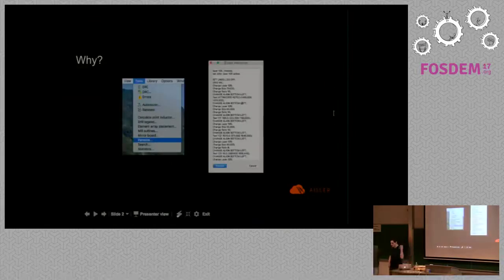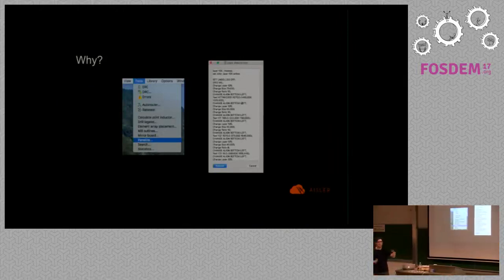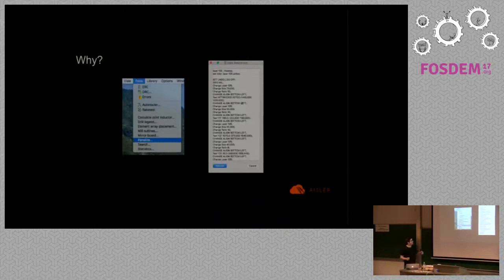So has anyone of you seen these windows here? They are out of Eagle, CadSoft Eagle, Autodesk Eagle, whatever you call it. The resolution is quite bad. If you do not recognize this, these are the windows to panelize a PCB. If you want to order them at a PCB fab and you only have a tiny one, you add some more to get a cheaper price. You can do this in KiCad 2 using the Python scripting functionality.